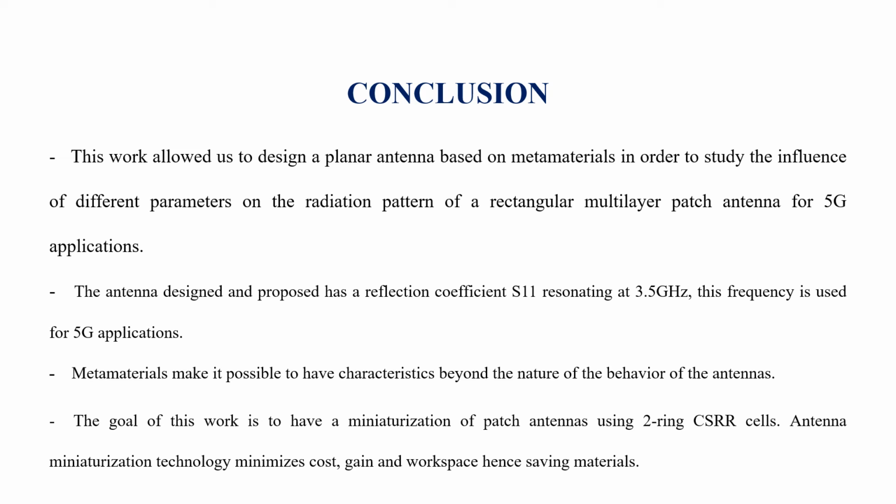This work allowed us to design planar antennas based on metamaterials in order to study the influence of different parameters on the radiation pattern of rectangular multi-layer patch antenna for 5th generation application. The antennas designed and proposed have a reflection coefficient resonating at 3.5 gigahertz. This frequency is used for 5th generation application. Metamaterials make it possible to have characteristics beyond the nature of the behavior of the antennas.